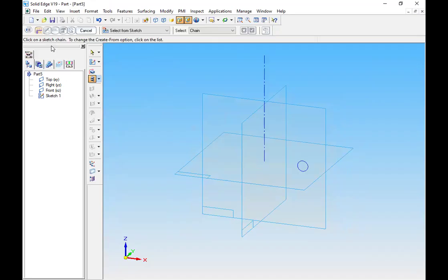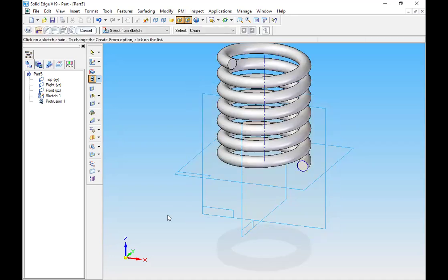Okay, once you select helical protrusion, first it will ask for profile to revolve, accept, then axis for revolve. And the starting point of the revolve. So it will ask for pitch. So I have taken already 10 dia. I cannot give less than that. Right? It should be more than that. So instead of 10, I'll give 15. Enter. Review. Finish. Okay. So this is called helical protrusion.